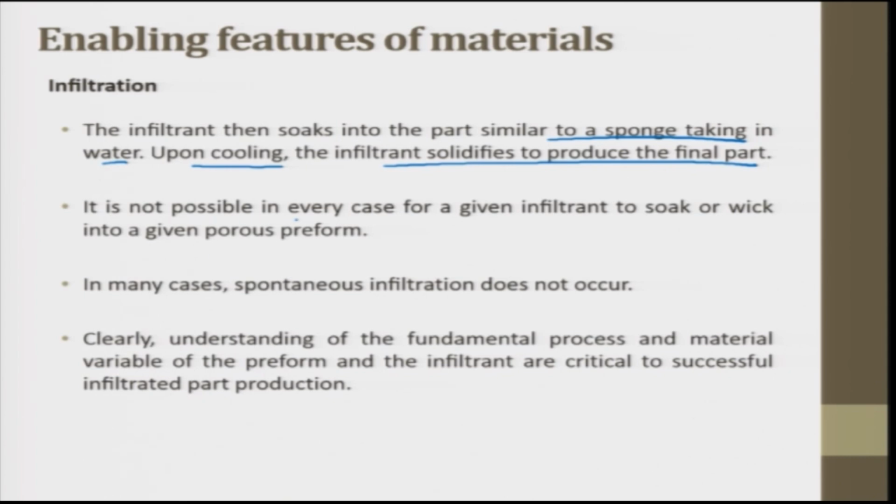It is not possible in every case for a given infiltrant to soak or wick into a given porous preform. So the affinity between the materials is an important factor here. A sponge can be put in water and it can be soaked completely, but can the sponge be soaked in some highly viscous material, maybe engine oil or some other material, that is not able to infiltrate into the pores of the sponge? So those things are similar in rapid manufacturing materials as well.